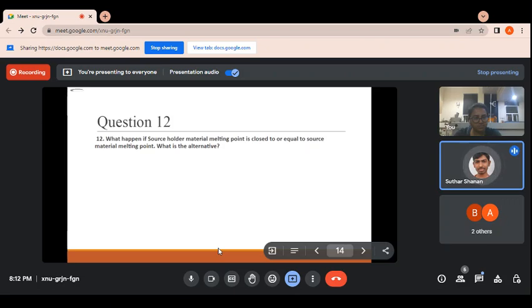Like SU8 is used for creating the channels for drug delivery, drug screening, the interdigitated electrode. In that, SU8 will follow the soft bake, hard bake, and photoresist mode. In other applications, SU8 will follow, as normal positive or negative, first soft bake, then photoresist development, and then hard bake.